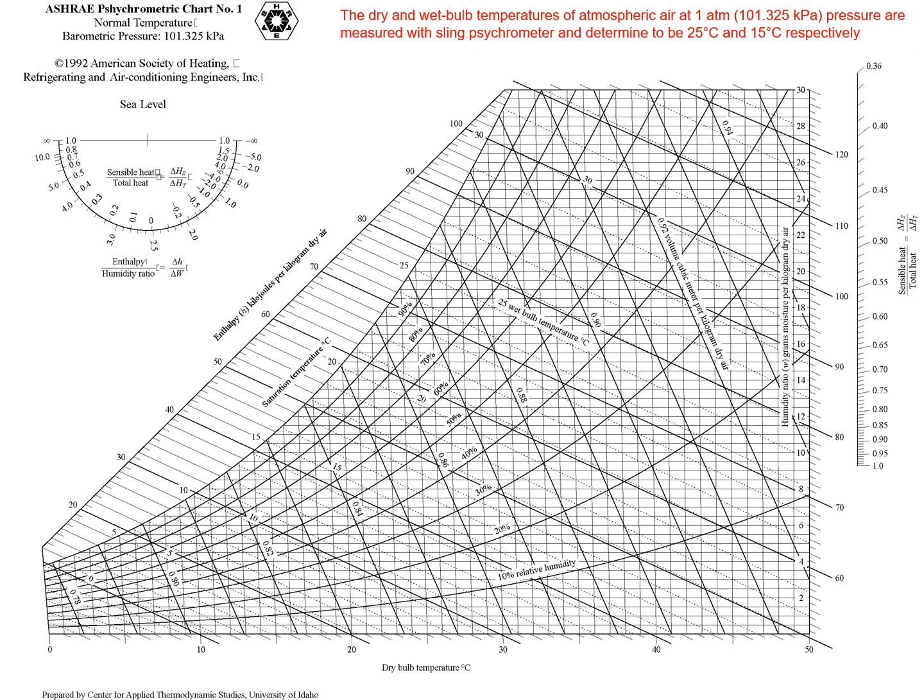This is the psychrometric chart. Now remember, based on the question, you are given 25 degrees C as the dry bulb temperature, 15 degrees C as the wet bulb temperature, and the pressure is given as 101.325, which corresponds to this. We are very confident that we can use the psychrometric chart because the pressure corresponds to the pressure that is stated here.